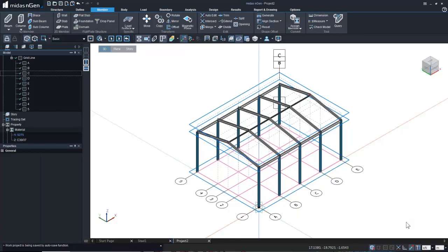Sorry, this is how it's supposed to be on. So, right, let me press undo. Yeah, so here we have auto intersect. You need to take care that your auto intersect option is on so that your sub-beams or your elements are generated with automatically intersecting intersections. So here we go, we have automatic intersection of all these elements that we just created. Alright, so that was about the sub-beam. That was just one created right now.